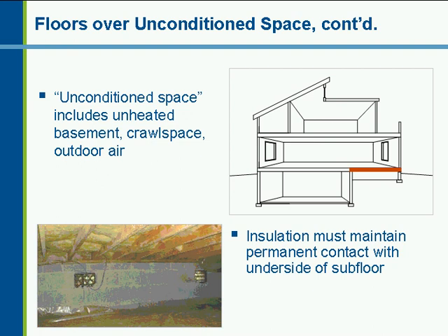One final requirement, the insulation in the floor framing members, if it does not completely fill the cavity, the gap cannot be against the underside of the subfloor. The insulation must be pushed up to be in substantial contact with the subfloor and held up by one means or another. That's to prevent airflow up above the insulation, which could short circuit its insulating ability.